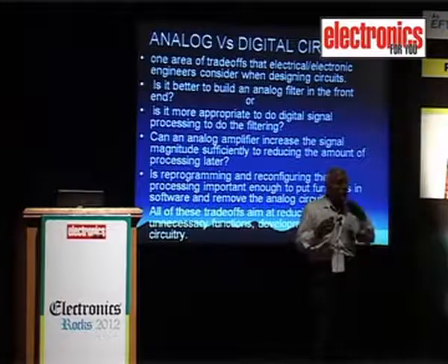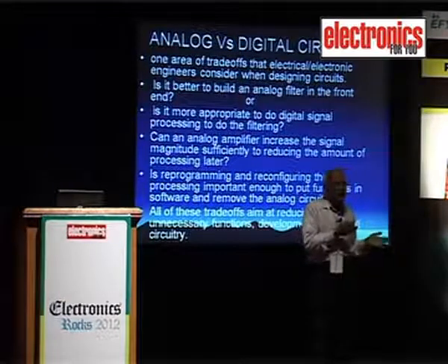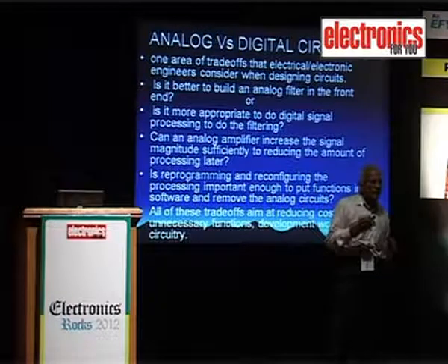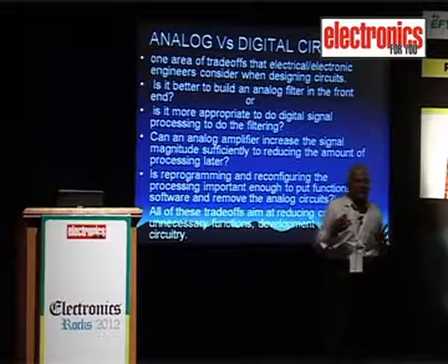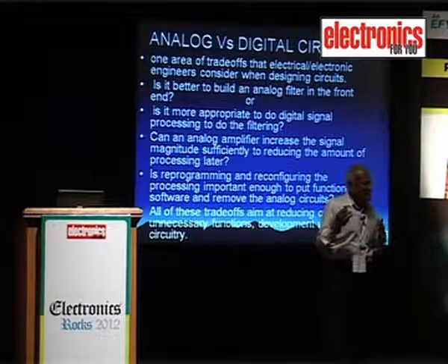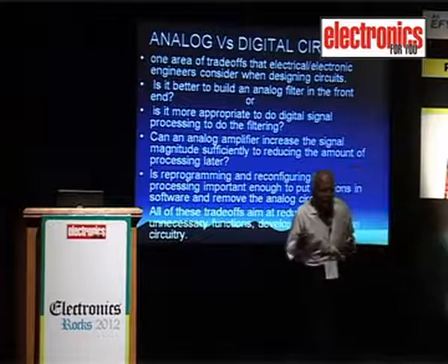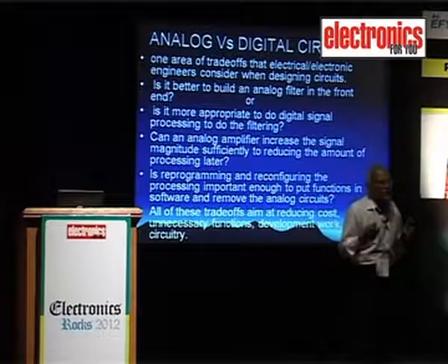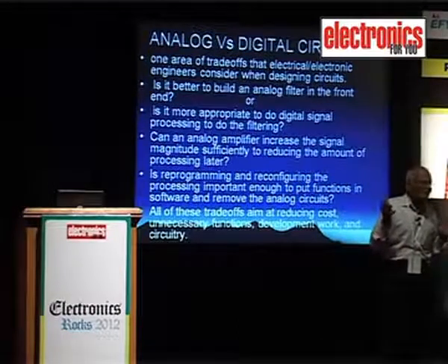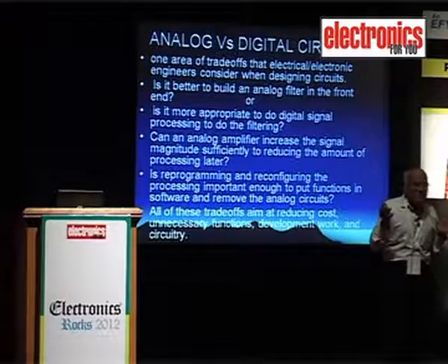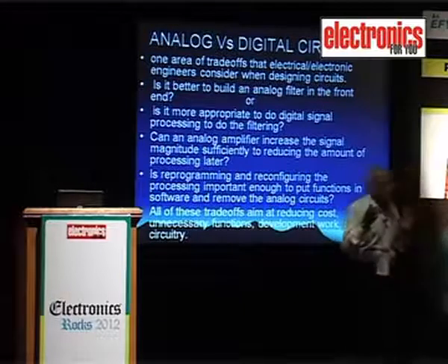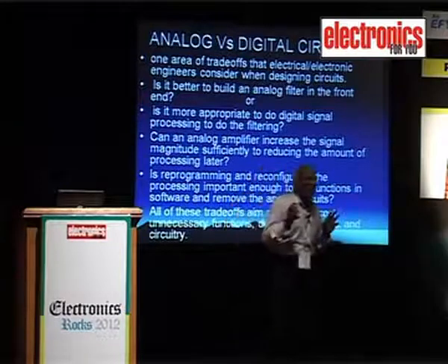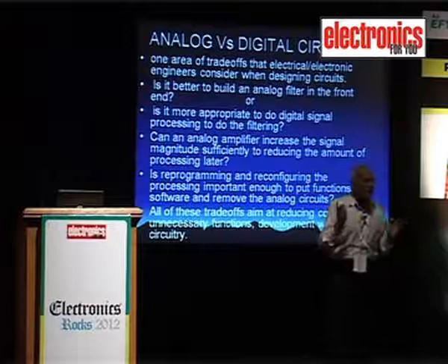But at 51.2, when you put it on boost charge, that is at the end of Saturday, you put it on boost charge. It so happened, on Saturday morning somebody put it on boost charge, he didn't come back to the station. Monday was a holiday, and Tuesday morning he came back and found the battery was on boost charge. You know what's the voltage of the boost charge condition for a battery of 24 cells? Any guesses? 66 volts. And why is the specification 53 volts, 48 plus minus 10%? And why is it 63 volts? All our 100 transducers got burnt.